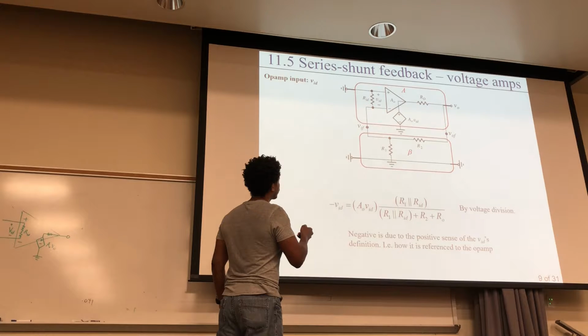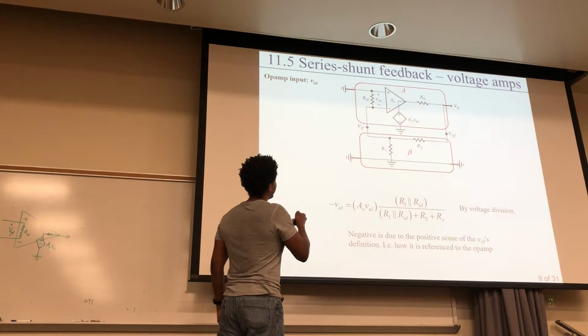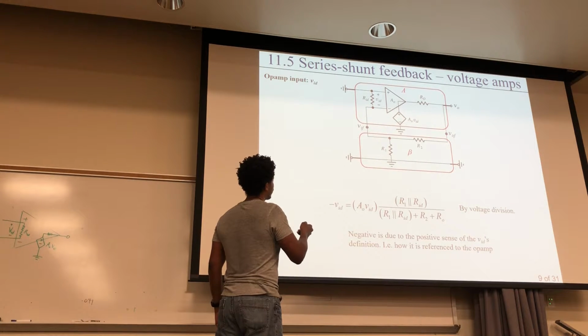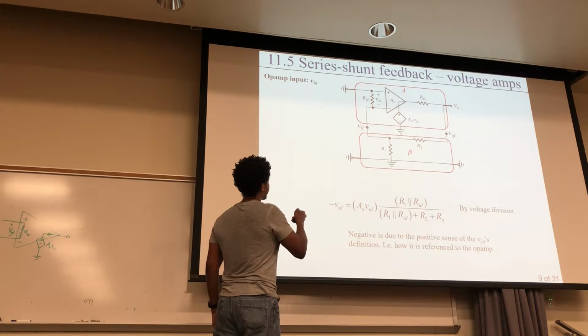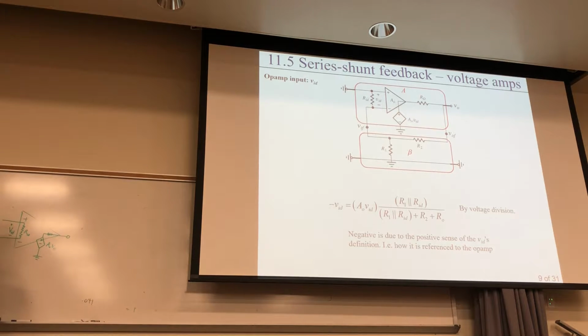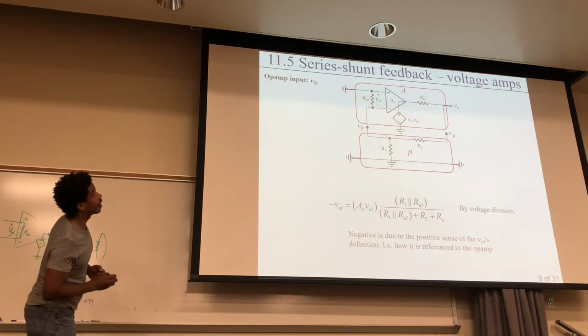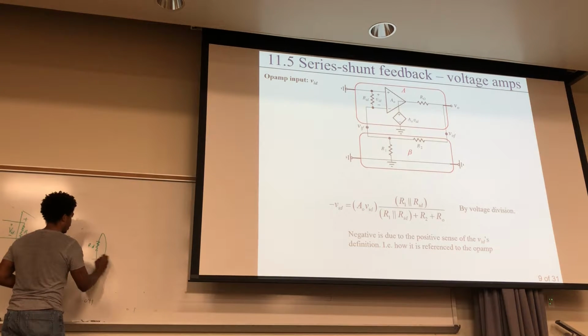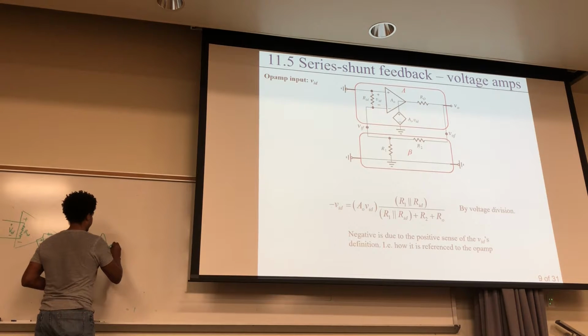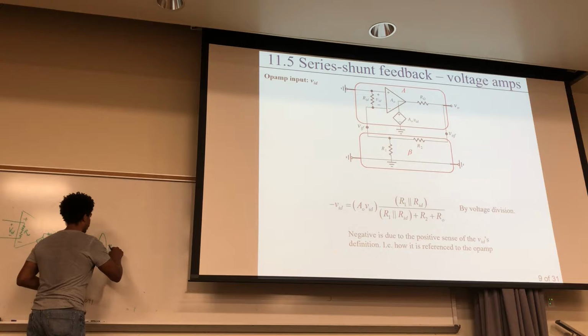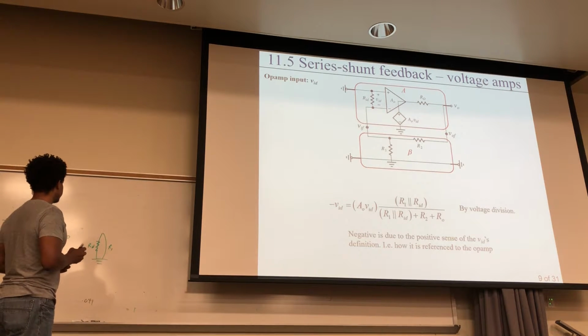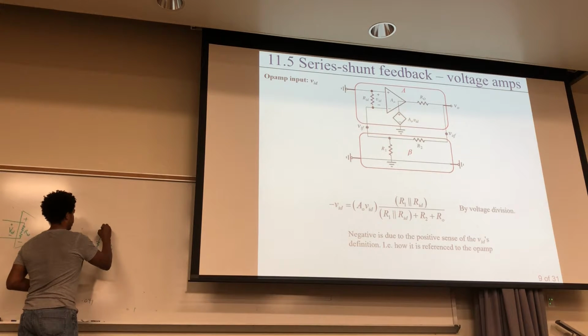So this voltage all along here happens to be this. Well, if this is 0 volts, now going downhill some VID, this is going to be some negative voltage right here. But anyway, this right here is the top node for this node and this node. And both of them go to ground. This one goes to ground this direction, this one goes to ground that direction. So if you wanted to, you could write it out like this, where here's one path to ground, here's another path to ground, and one is RID, and the other one is just R1.